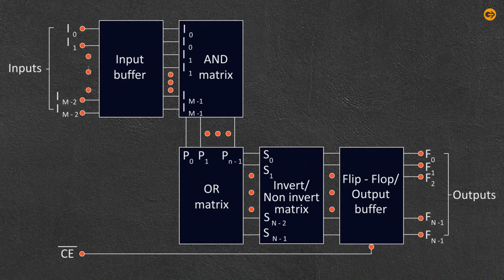Programmable Logic Array or PLA and Programmable Array Logic or PAL. PLA. The internal architecture of the PLA device is given. The PLA consists of AND and OR gates in a single chip. The number of gates and their inputs are fixed in a PLA chip. The AND gates are used for the product terms, whereas the OR gates are used to sum these product terms, thus generating an SOP form of expressions.